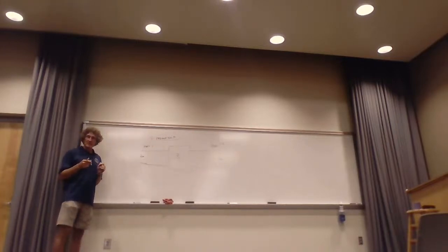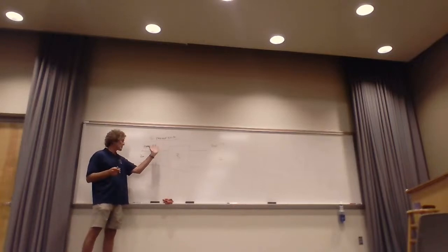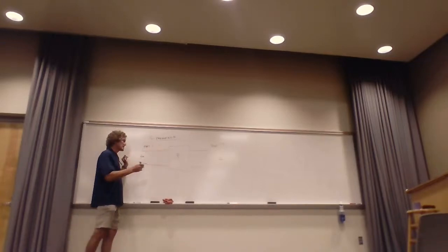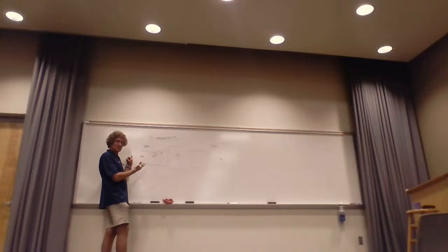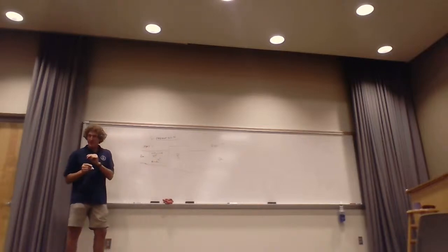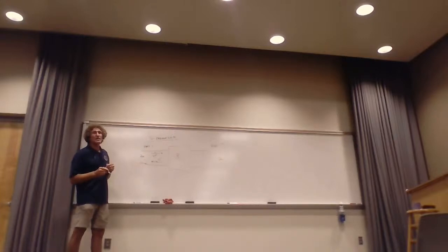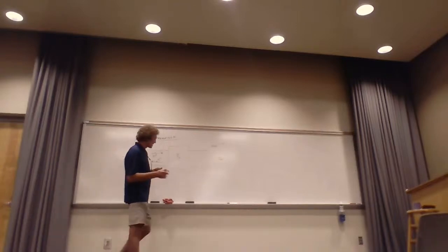Since we're talking about transmission lines, and we are when we do S parameters, we've got something propagating this way in the transmission line on the first one, port 1. Something's reflecting. They talk about the incoming voltage waveform. They call it V1 plus. I'm just showing you this in a bulk manner. There's also going to be a reflected voltage called V1 minus. That should make logical sense to you. We know the relationship that V1 minus over V1 plus is the reflection coefficient. But for now, leave it at that.